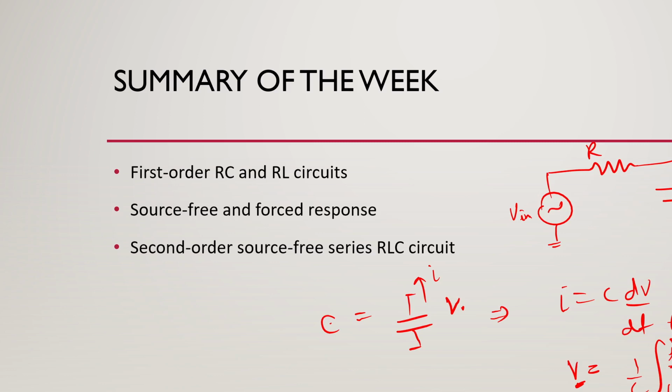That is why you say that this particular element has memory. What is indeed meant by memory? Memory means you are remembering the past, right? So the capacitor also remembers the past. The voltage across it is not only a function of the instantaneous value of current, but also the previous values of current. That is why the capacitor is a memory element.